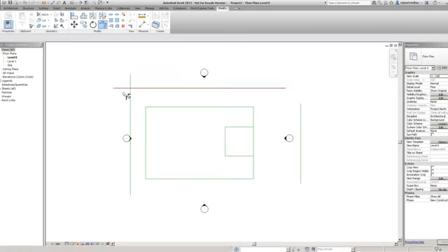Want to trim these two little bits away, neaten this corner up? Select that line, it cuts it away. Same in this bit. It keeps me in the command. Select that line, hover over that one, and actually soft select, and that shows you how it's going to do it. Left click, done. Couldn't be easier, very, very simple. Just Control Z to take that away a little bit.